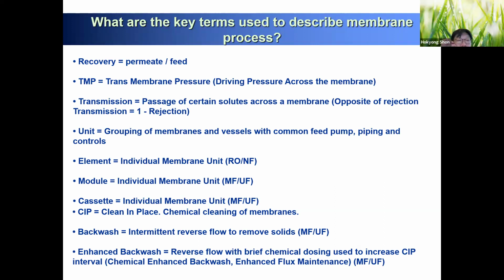And cassette and CIP, cleaning in place. So you need to clean the membrane because of inorganic fouling and organic fouling. So we need to have a cleaning in place, backwashing, enhanced backwashing. So that's the RO membrane design.